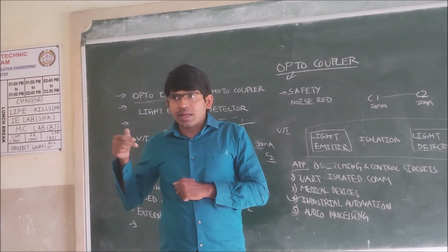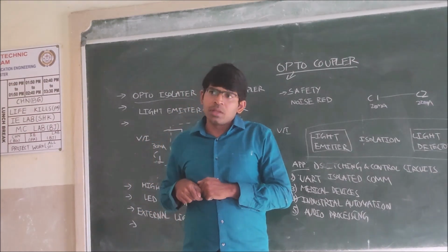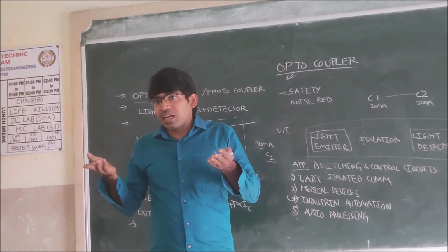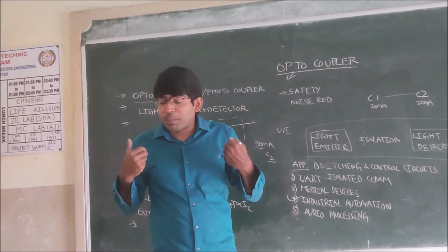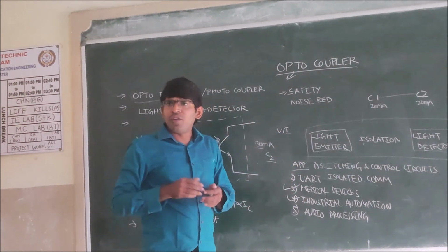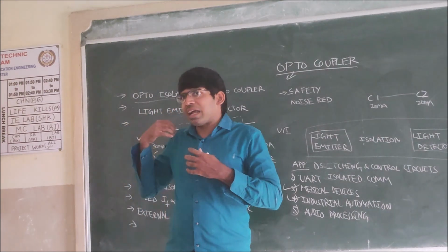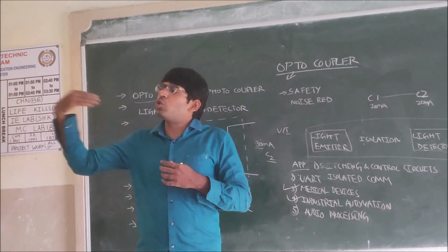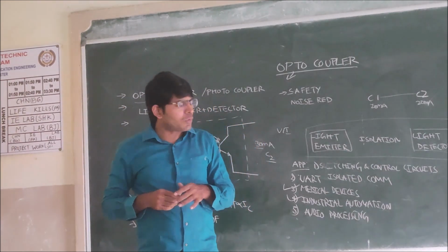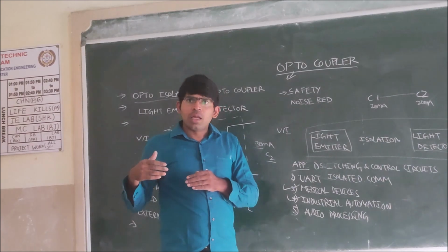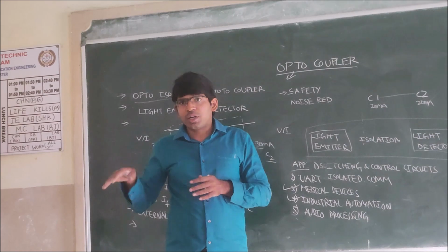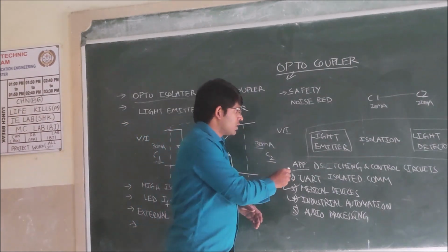If they are in touch, that extra voltage might affect the patient, because these devices are directly fixed to the patient. So in medical devices, where the patient-connected electronic devices should be isolated from the outside electronic devices, we use the concept of the optocoupler. Only these devices should be separate, isolated from the outside devices.